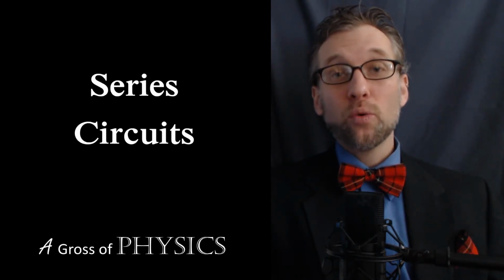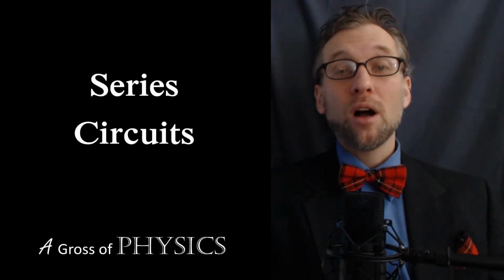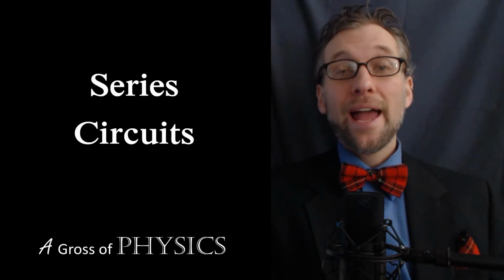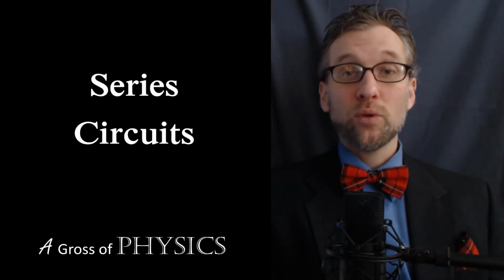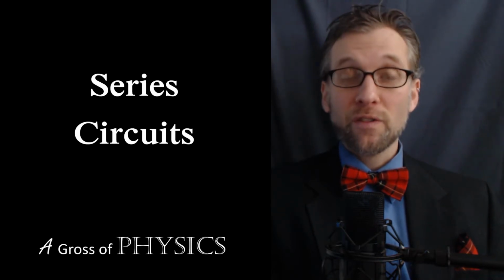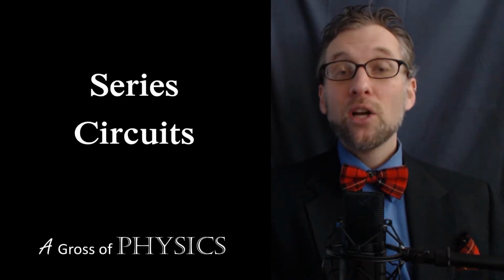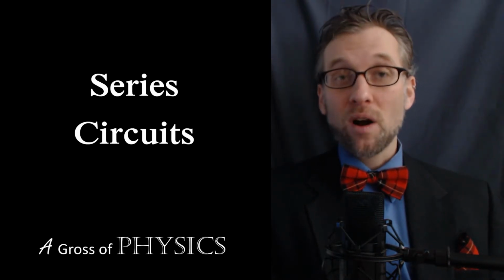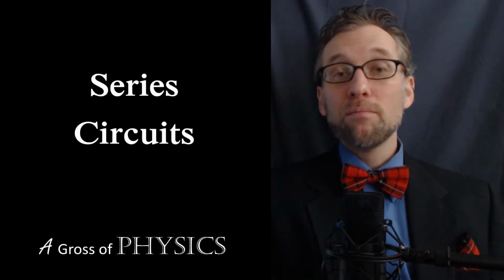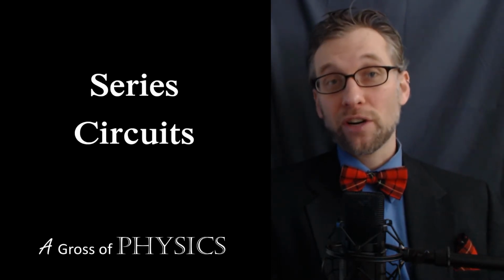Today is day 121, and what I'd like to do today is discuss series circuits. Now, we've already discussed Ohm's law, which is V equals IR, and the power and energy equations, which is P equals VI or E equals PT. Of course, there are other versions of the power and energy equation, but our standard is P equals VI. So we have two equations, V equals IR and P equals VI, that cover most of what we can use to find different variables in a circuit.